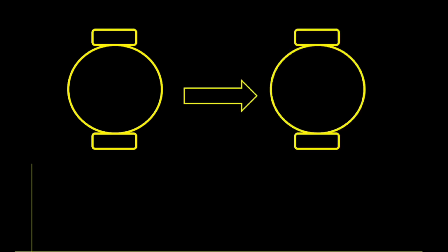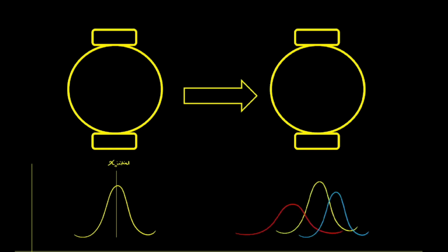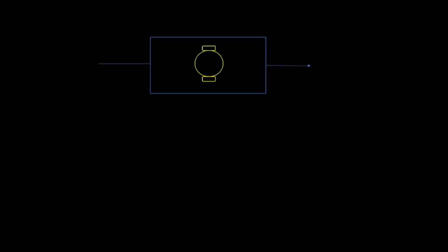Let's say we have a robot which has a differential drive. Here we consider it as a unicycle model as we are doing a simulation. We consider it has moved with some input u, and we are considering it as a Gaussian probability and Gaussian estimate. So here we are talking about how we will get a predicted state estimate, how we will get the measurement of the model, and how we will predict the proper estimate of the robot when we give some amount of input u.